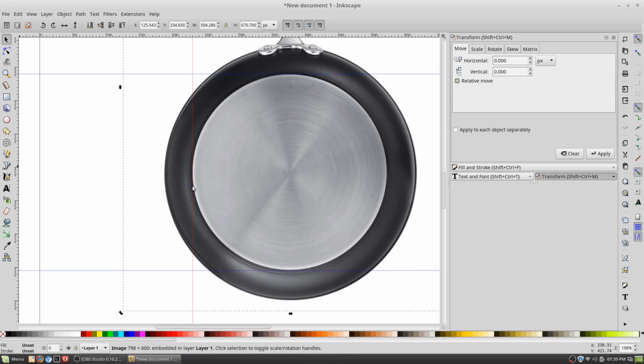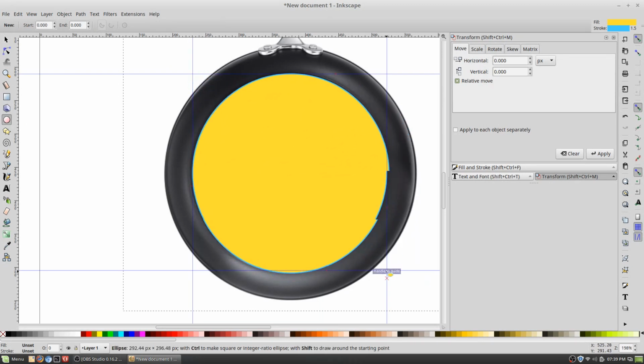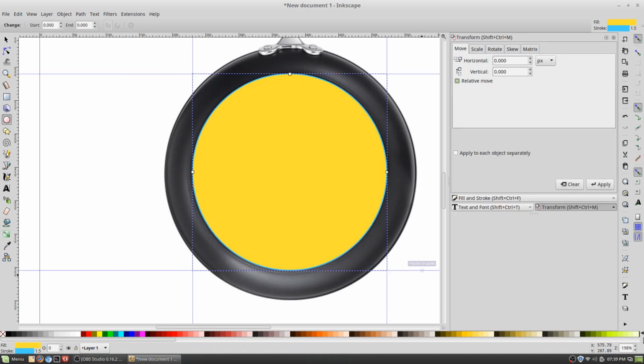Now there are tools that will allow you to take an image and cut it into paths. It does not seem to work on this particular image because it is a solid JPEG and the program sees it all as just one giant white thing. We'll use that for another application in a bit. But for now, I'm going to put my 4 guides over there, and then grabbing my circle tool, I can actually start from up here in the corner and drag down to the bottom corner. Things will snap pretty close to grid there.